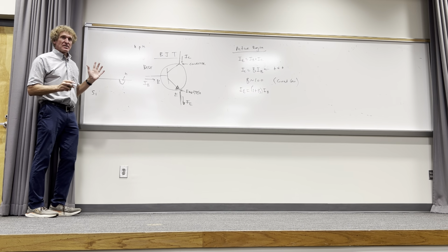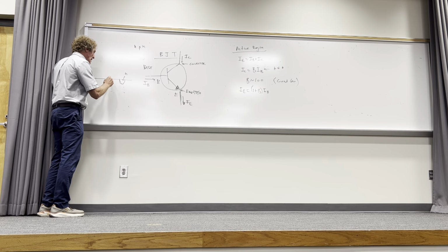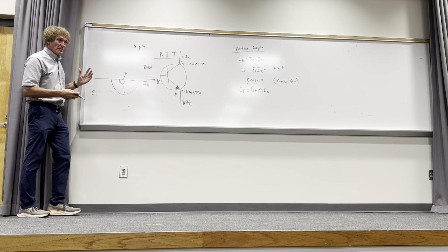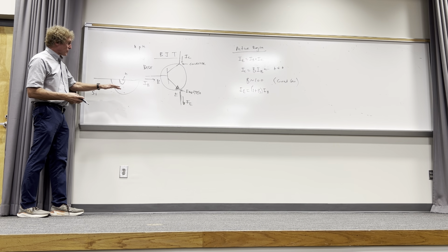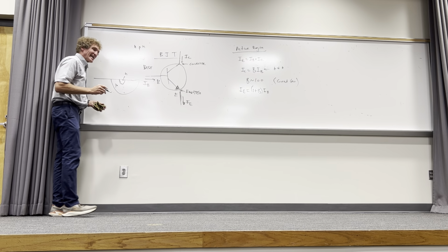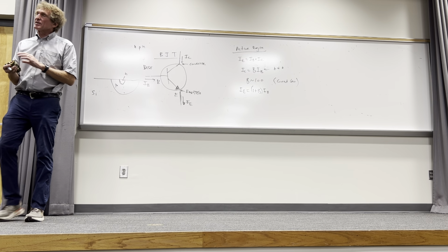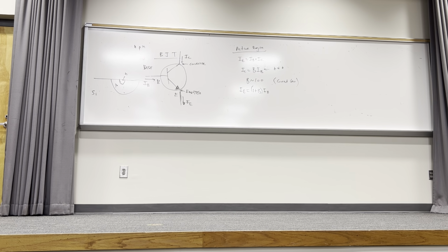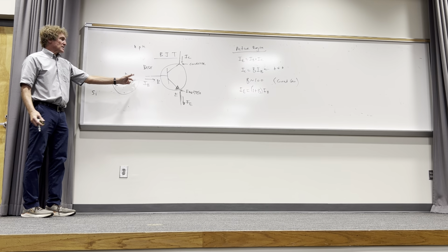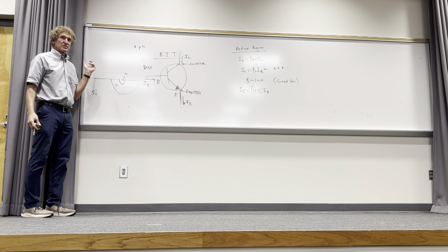So there's N-type material here. Then it's surrounded, and this is all done by diffusion, where when they form this, the first thing they do is form the base. They diffuse a P-type material right there, but the density of the P-type is much less than the N-type for the emitter, and they diffuse this in there by putting a mask on the upper part of the transistor.